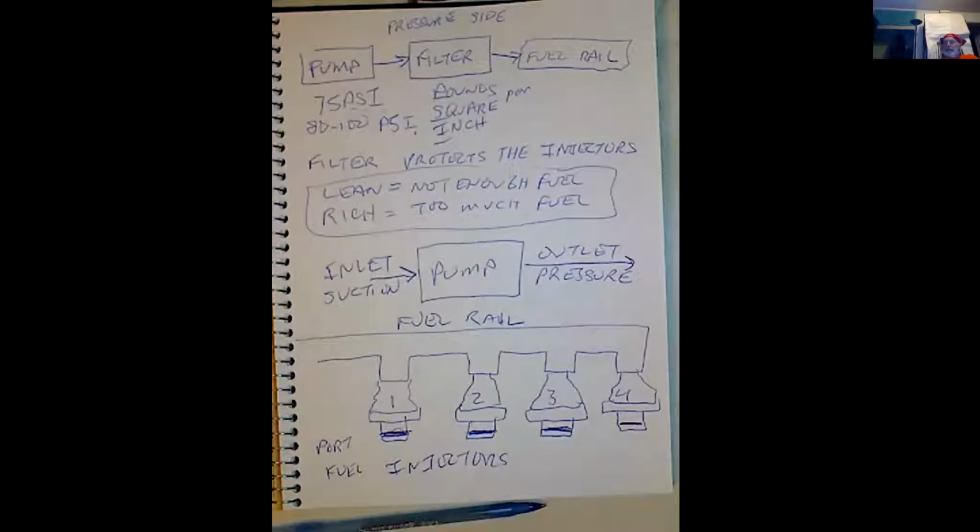But what happens after the intake stroke? Compression. Why do we have a compression stroke? To compress the mixture so it can fire. Well, it'll fire anyway, but it'll fire a lot more efficiently if we change all those fuel droplets into a vapor.